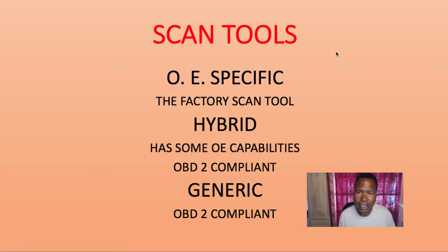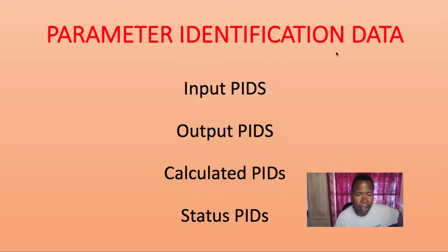Okay, we talked about scan tools earlier. OEM specified scan tools, hybrid scan tools using hybrids, generic and manufactured scan tools. Right? Most scan tools today have to be OBD2 compliant. Then on the scan tools, we also talked about input PIDs, like any sensor will be an input, sensor or